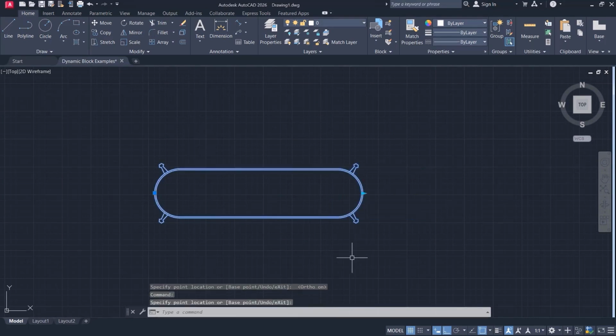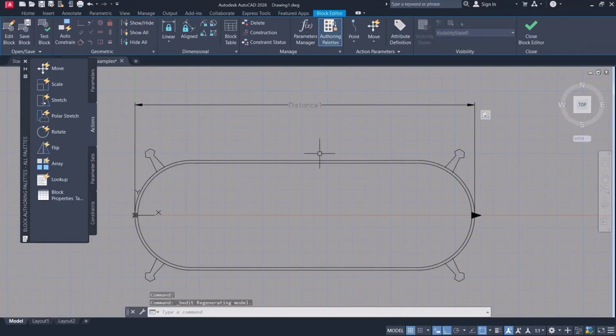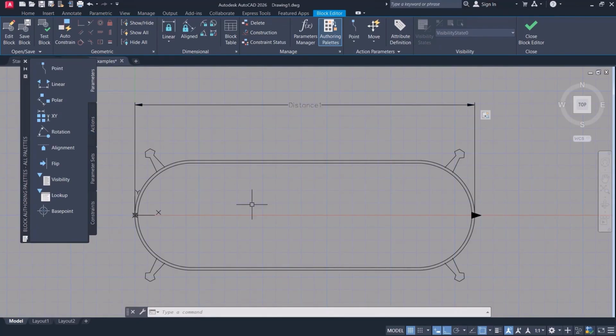What's the difference between this and the stretch we had in point mode? We could change the scale in all directions, or scale the whole thing, even though it would get deformed and was not really useful for us, but still, we could move it around. Here, because the parameter is linear, it is only in the lengthwise or horizontal direction that we can increase the length for the table. Now, look, I could resize my table without any limitations, using arbitrary numbers, whereas in reality,